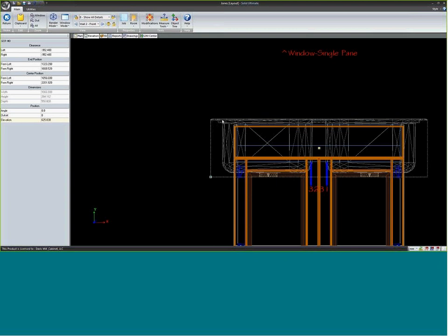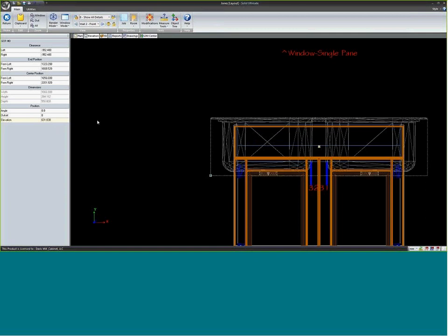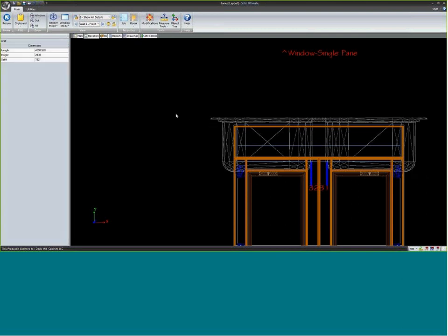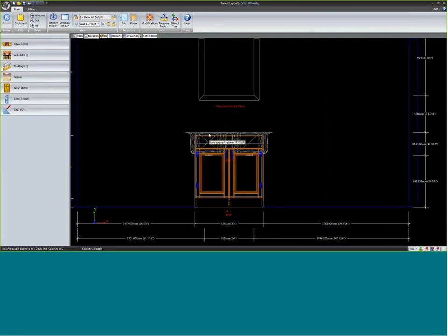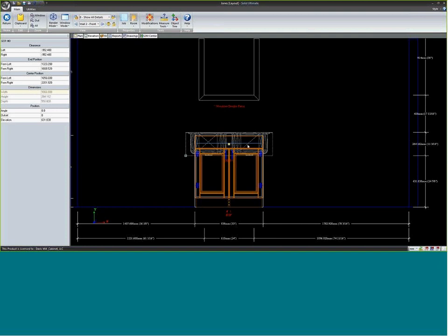The countertop will be flush right out of the top of this. So typically you're going to want to be just a little bit higher. So let's say 1/4 inch up. So now if I were to put a countertop in my drawings, I would see a countertop come just underneath this sink lip. So that's placing a sink in here using some of those centering and our XY coordinates and stuff.